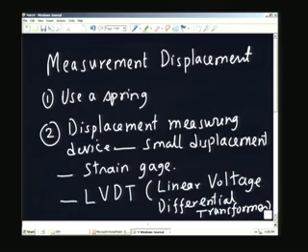The strain gauge, in this case, resistance change is measured. Electrical resistance of an element undergoes a change when it is subjected to a displacement, and therefore, what I am going to do is I am going to have one more transduction or one more transducer action. Pressure gives rise to a displacement.